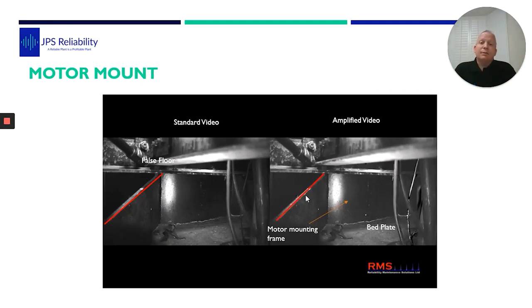So then we had to work out, well, how do we stop these motors failing? The easiest option would be just to speed the motors back up to the highest set point, because they ran fine at that for years and years. That wasn't an option because energy efficiency dictated they had to run lower. Next would be redesign of the pumping station. Put in, instead of a cardan shaft, motor and pump, just a standalone submersible pump set down below and let that run.